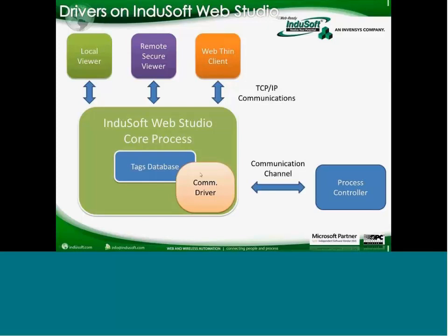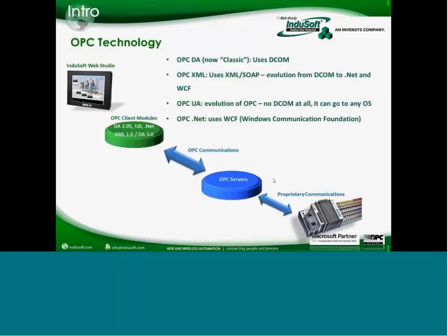So basically, the communication driver is one of the tasks. If you're talking about OPC, here you have our OPC client talking to a server, which is pretty much what you had here. So if you talk about OPC specifically, you have the device on this right corner here. The OPC server talks to the device using whatever proprietary protocol that device speaks. Through OPC communication, our client module is going to get the information from the server and then feed the tags database. From that, you get to the screen. And again, here is the list of the OPC options that you have with InduSoft Web Studio as part of our offering.